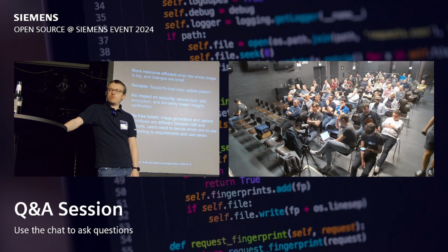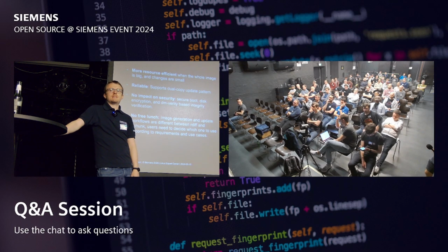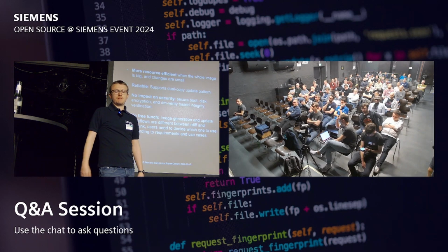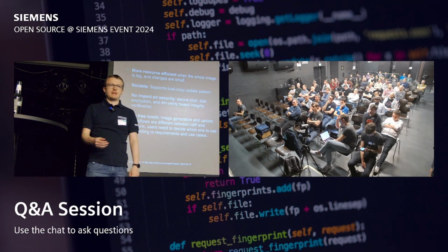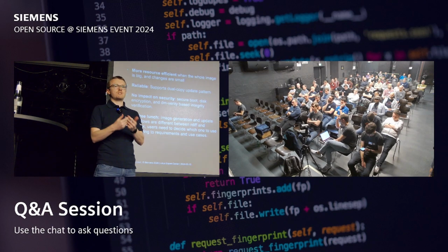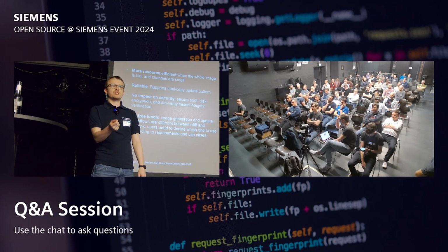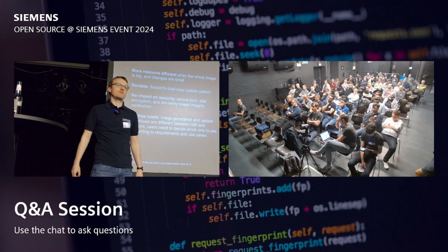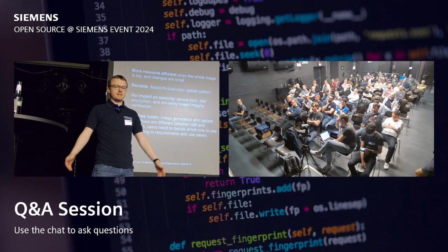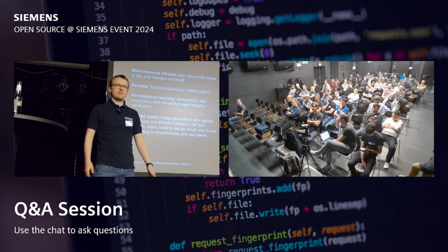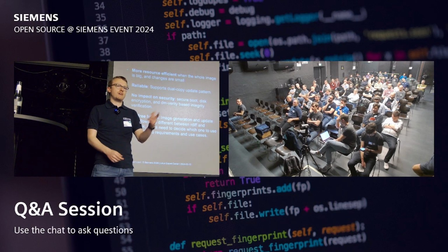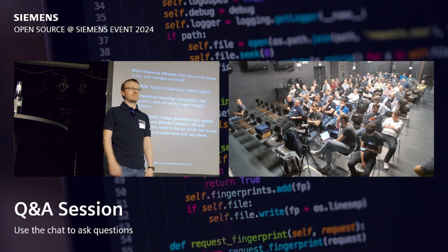But one thing that is often forgotten is that from a workflow perspective, you can still decide later on if you want to do a delta update or not. You can still upload a full image and the system will happily accept that and flash that, because all the logic to drive the update is included in this SWU file. And by that, if you see that your delta SWU file in case of the RDIFF handler is too big, then simply don't use it, simply go with the full update.